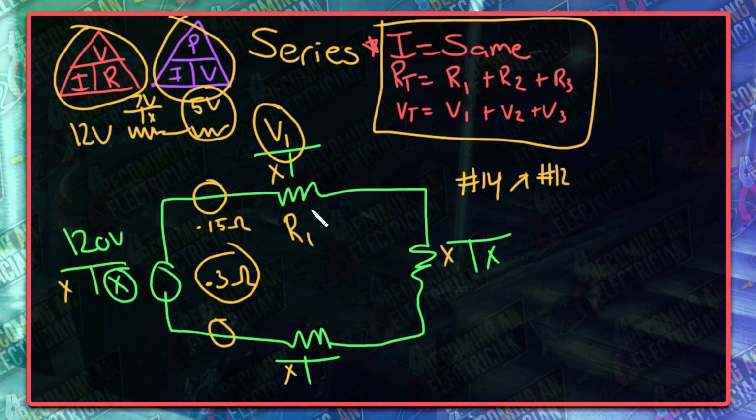Sometimes if it's a long length run, and that's sometimes to do with the utility company and yourself. You will hear about the 3% total voltage drop, and then I think the total is like 5%, but that's to do with the utility company. So not to get into that, but typically you will learn about the 3% voltage drop. We're not allowed to have any more than that. Therefore, we might have to upsize the wire.